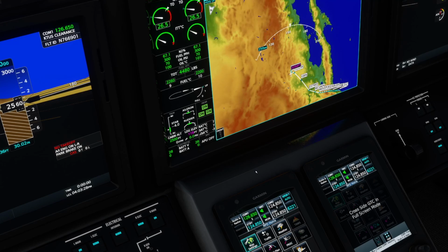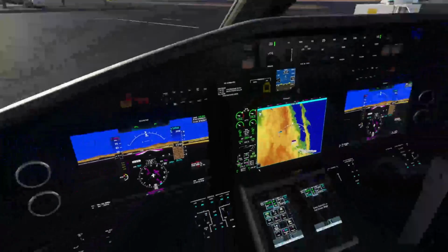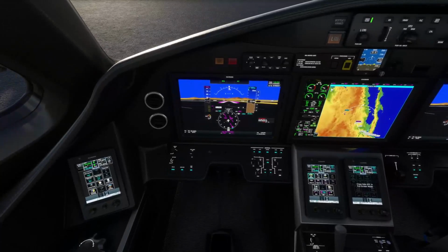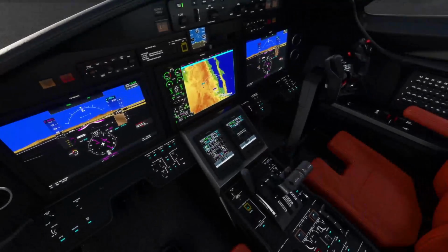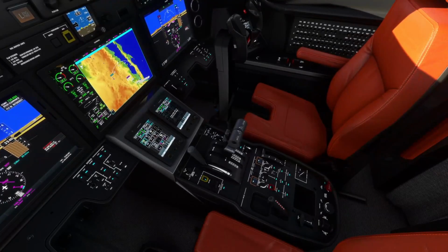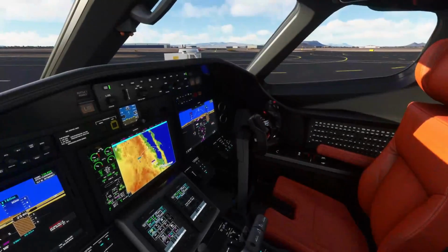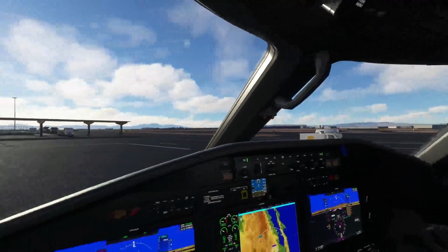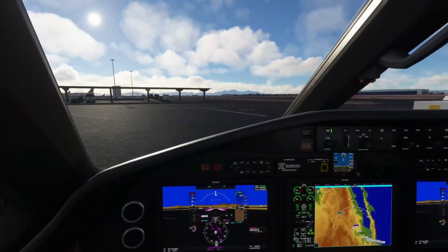There's 4 degrees. Alright, so we got our takeoff trim set. FMS is set. Flight plan set. Barometric pressure set. Transponder set. Taxi lights are on. Recog lights are on, engines are both running. Guards are closed. APU is off. Anti-ice we will leave off until we're ready for takeoff. Other than that, taxi lights set. Alright, I think we're ready to go.